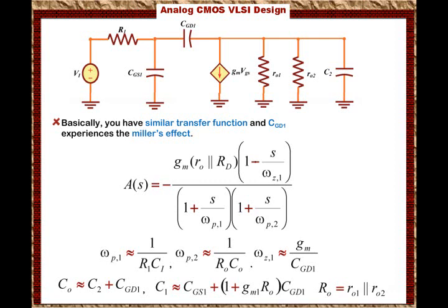Then we also said that the input impedance of this amplifier is a function of frequency because of the capacitances at the input. That means the input impedance drops as we increase the frequency, which explains why the gain drops as we increase the frequency. Then we also said that when we implement the circuit for IC design, we have to use active load.